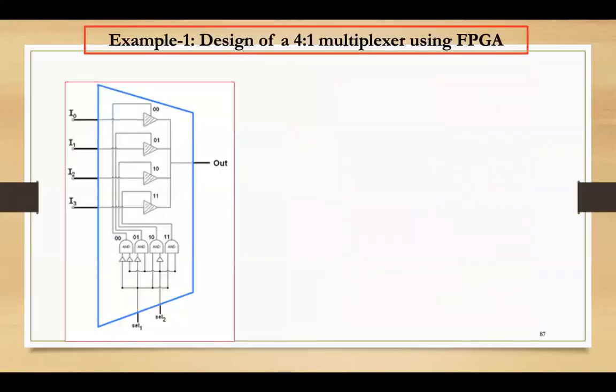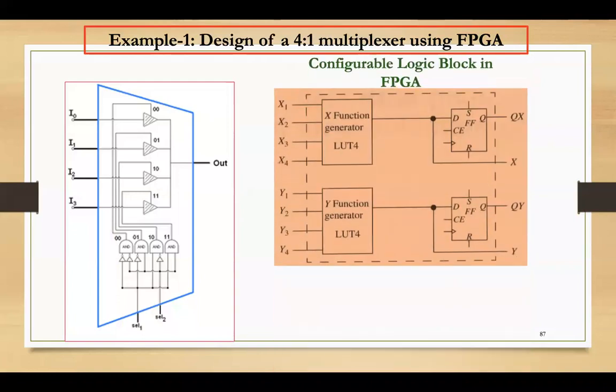Right. So now we will move on to designing with FPGA, right? So when I say designing with FPGA, how are we going to use this MUX, and how are we going to use the flip-flops and get things done? So always you should remember your CLB will have a function generator and a D flip-flop.